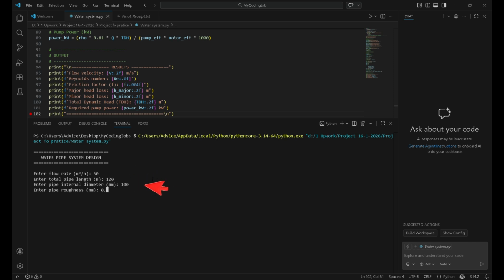Pipe diameter, 100 millimeters, DN100. A DN100 pipe is selected to maintain appropriate flow velocity, 12.5 meters per second, ensure manageable friction losses, allow compatibility with standardized fittings, and withstand typical industrial pressures. Diameter strongly affects Reynolds number and overall hydraulic performance.